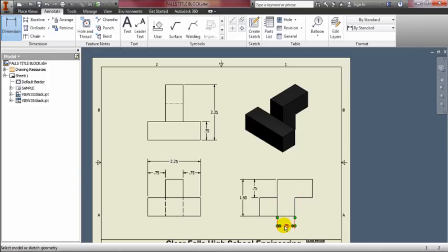This will be my last depth, and this depth is exactly the same as if I were to do a dimension right here for this depth, but I don't want to dimension to a hidden line. And now I have 1, 2, 3 depths, and I have 1 overall, and then 2, and then 3, and then 4 overall depths, so I've done 3 out of 4. So this piece would be fully dimensioned at this point and would be ready to save.